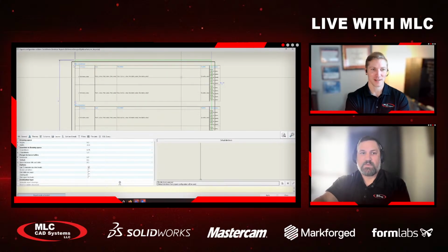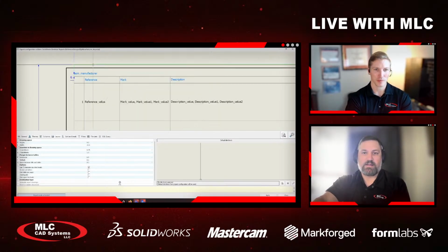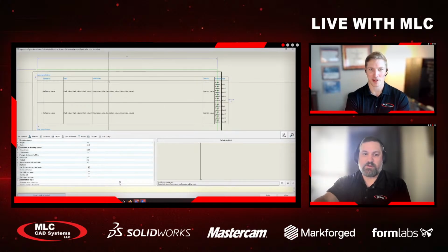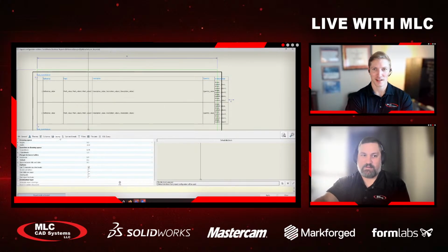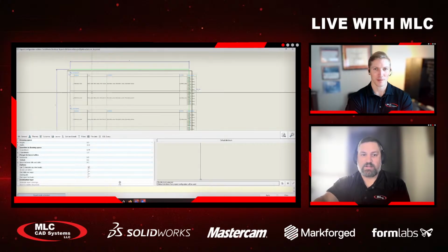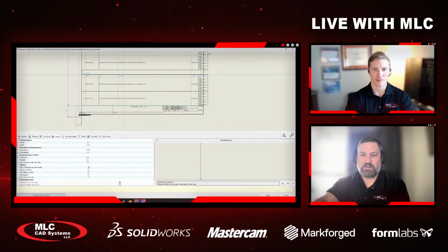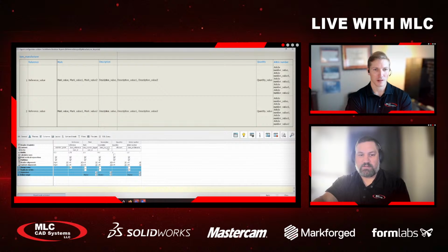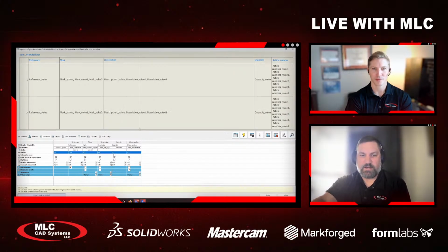And you'll see that this green area is the good area for you to draw on. It's based on your title block specifically, and you can see all the behind the scenes attributes and everything too. Now, for columns, I'm going to take this description, and it's 9.5. Let's make it 8.5. So it'll squish it down a little bit.